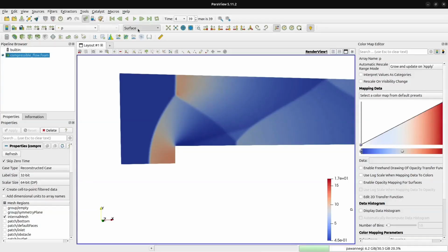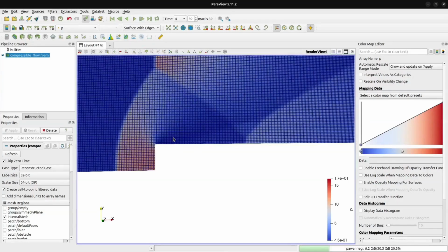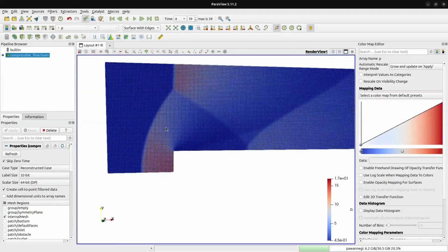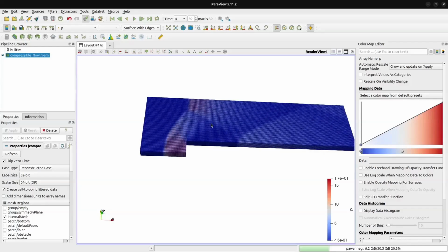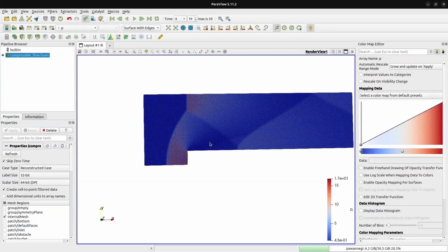But the thing to note here is the mesh is uniform. Here we can again generate a non-uniform mesh and try to solve this, but that will be very simple. So instead of this, let's try flow past a certain obstacle. We'll try to solve this using rhoCentralFoam, then we'll solve the same problem using rhoPimpleFoam, and we will see a clear difference: rhoCentralFoam won't be able to solve that kind of flow. Let's get started.